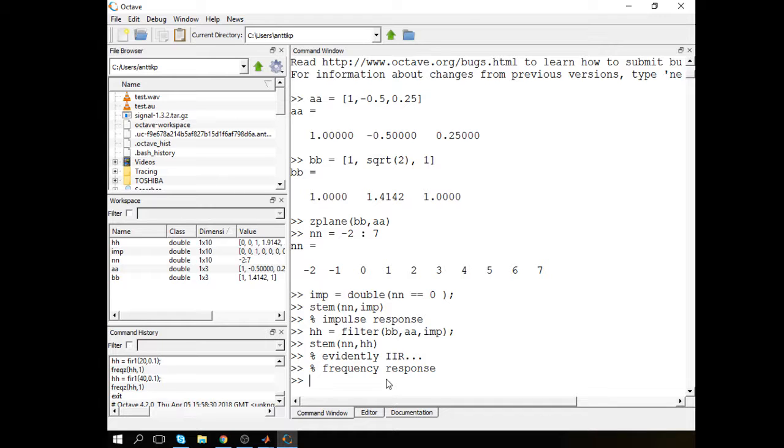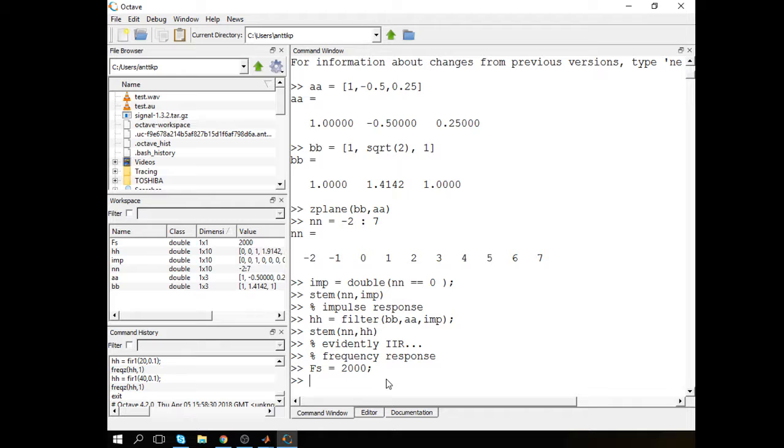If you don't know the frequency range where you are using that filter, then how much do you know about this system at all? So the fundamental thing, you need to know the sample rate. Just for fun, I'll put 2000 here, so 2000 samples per second. So this would be some, say, microcontroller-based data logging system,